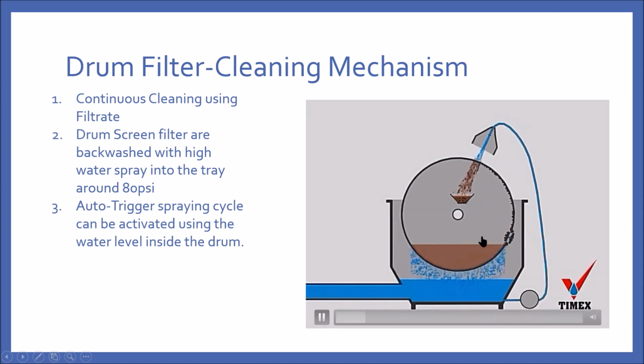Water will enter the drum filter in the middle, as explained earlier. As the drum rotates, it builds up what we call a filter cake. This filter cake will accumulate on the side of the wall, while clean water passes through the drum and is filtered. Firstly, it is important to control the pore size of the drum, as different pore sizes will give you different filtering capabilities as well as different flux.